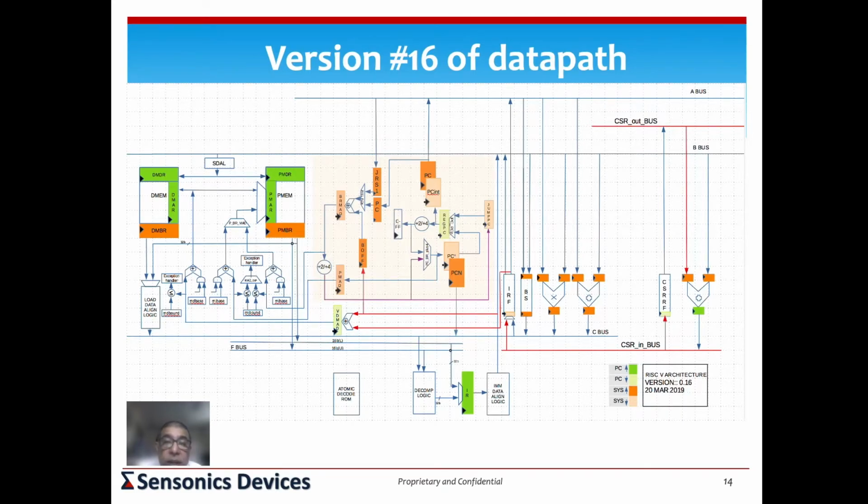So the integer register file can write the output from the C bus, either the barrel shifter's output or the multiplier or the adder's output, and write it into the register file, or it could take the output from the CSR, but it won't be able to do both together at the same time. So this detail is not shown. Somewhere you would write it down, and when you're writing the register transfers, you'll remember.